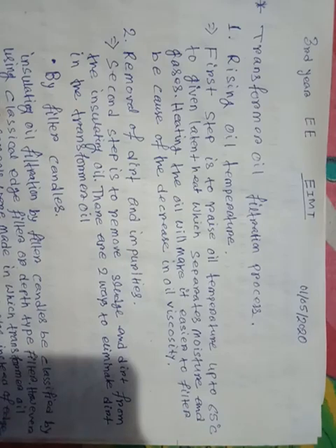Today we will learn about the filtration of transformer oil, how to filter transformer oil. The filtration is done by different types of processes. The first step is to raise the oil temperature up to 65 degrees Celsius.